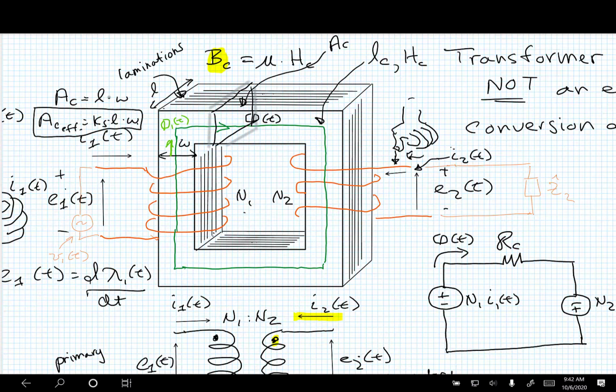So basically, what I'm asking you is this. Here's your BH curve right here. You're operating right here at no load. When you draw load, do you want to go up the curve or down the curve? That's the question.